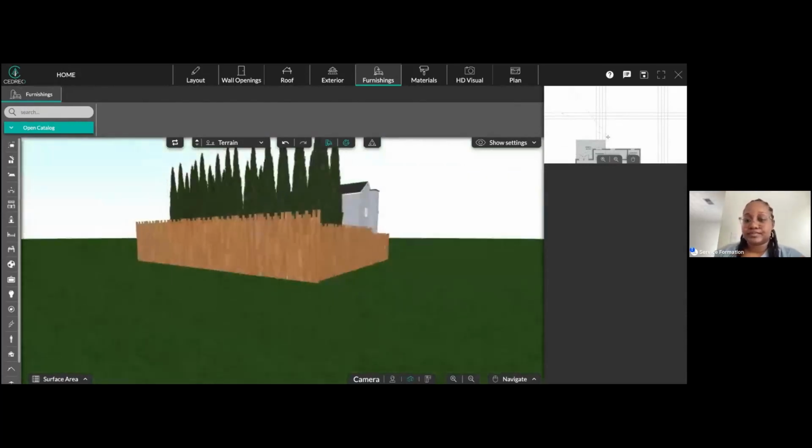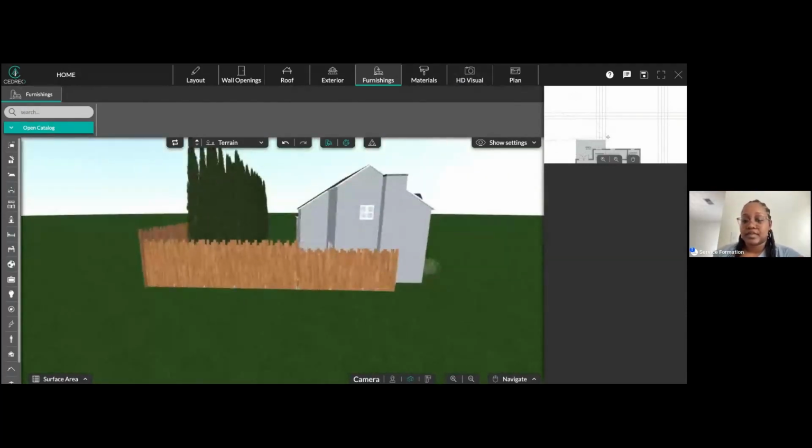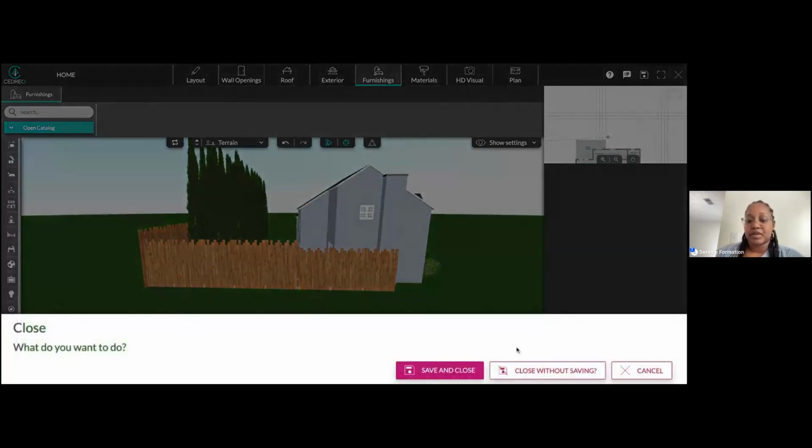How about using an embankment? Okay, let's go back to, I don't know if you saw when I used the embankment. Once you set your terrain and the slopes for your terrain, the embankment becomes automatic.